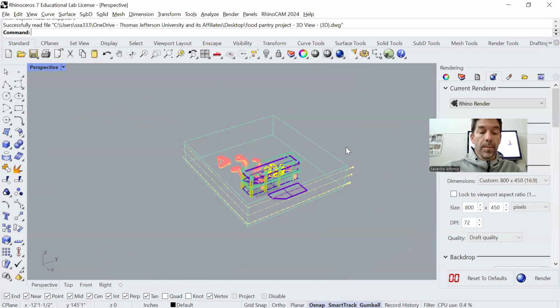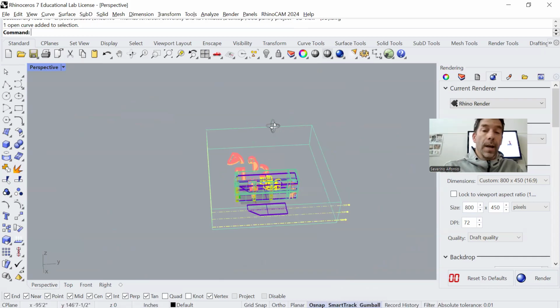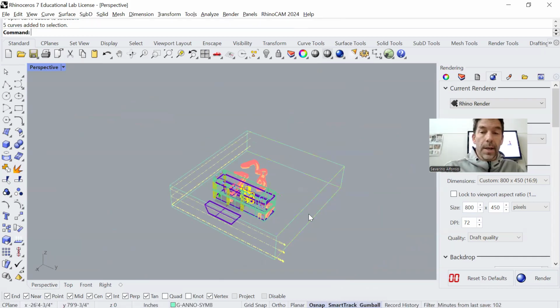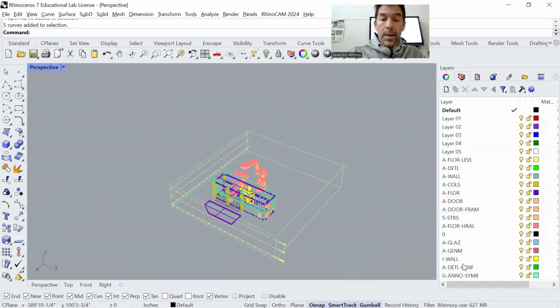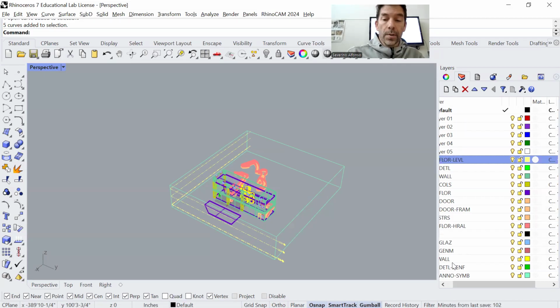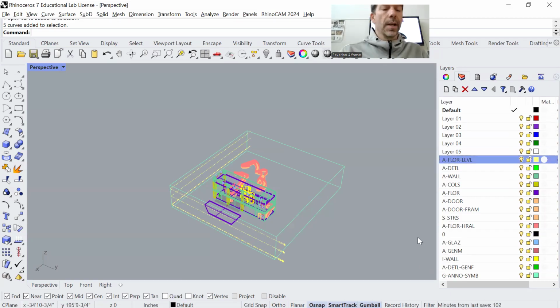This is the import. Notice how the section box is there. You might want to hide it. You didn't want that, so you can delete them now. You hide the layer. The layers are the same as in AutoCAD. So they go by color, and they also go by category, as in architecture, structure, interior walls, et cetera. The first letter is pretty much the logic of those.